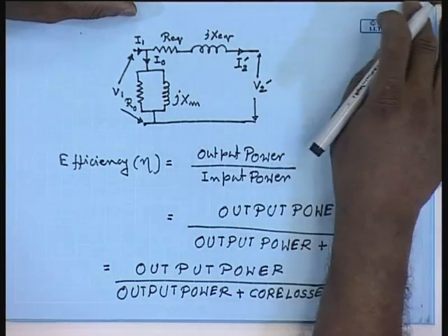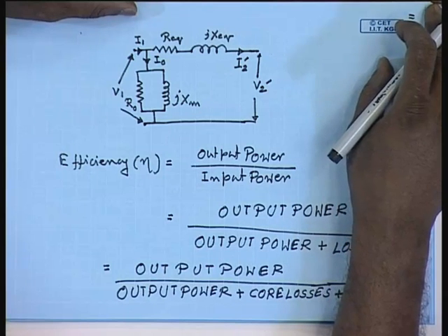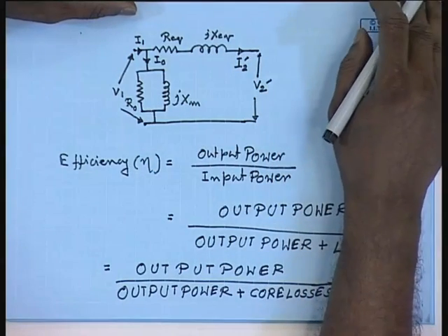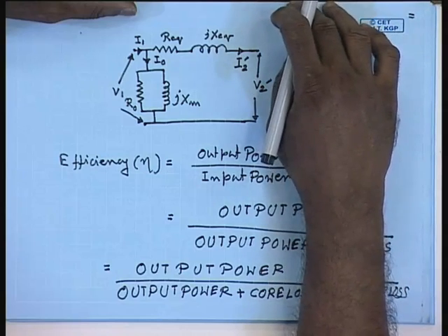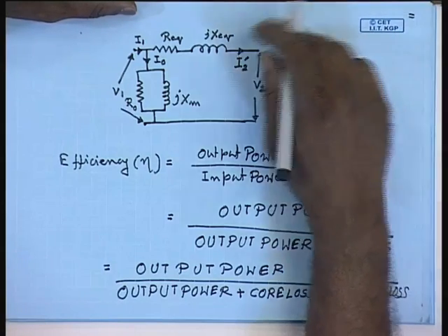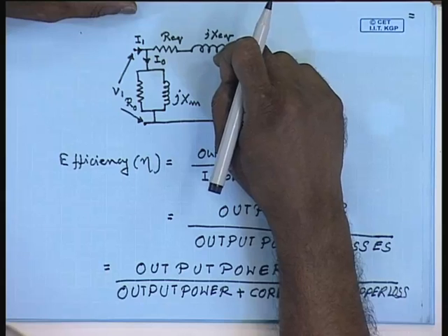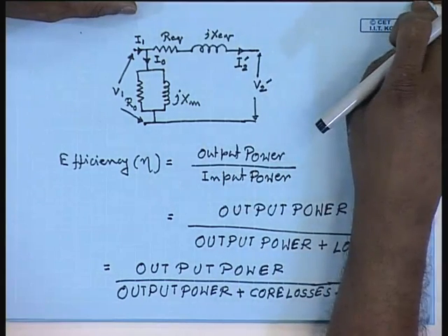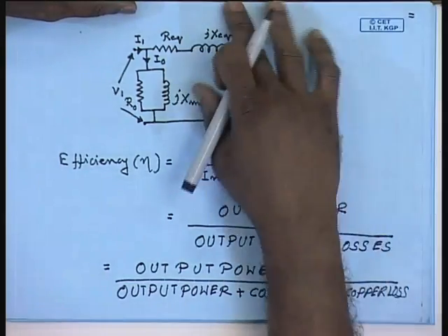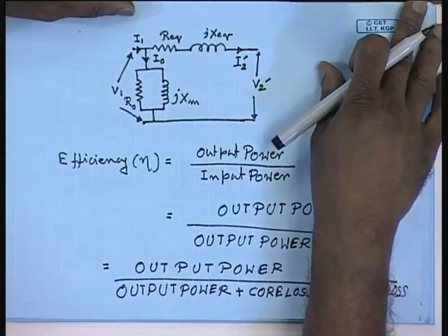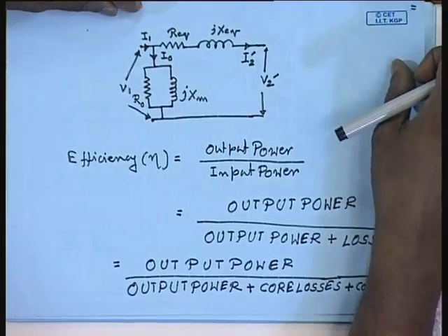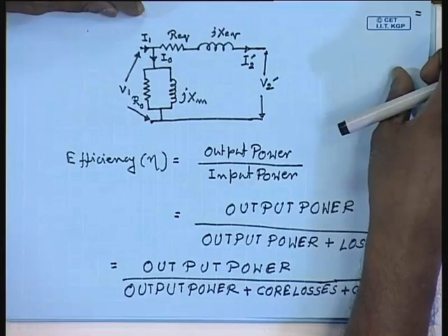We have seen that in the open circuit test, we connect a wattmeter, the wattmeter reading is equal to the core loss, because there is almost no current flowing in the transformer, the no load current is very small. Similarly, from the short circuit test data, we argued that the magnetizing current is very small, therefore, the core loss is very small. So, the wattmeter reading actually represented the copper loss. Now, short circuit test is usually done at the rated current, therefore, the value we get is the full load copper loss from short circuit test. Similarly, from the open circuit test, we get the iron loss, which is independent of the load current and constant.